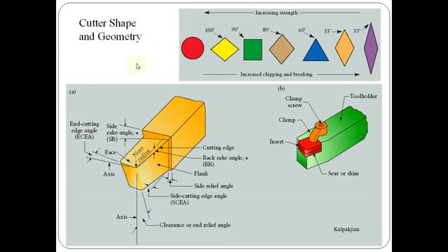So the cutting geometry as well as the shape of the contact point plays a major role. As we see here, as we move from the very sharp end to our blended one, we may have a higher strength, but the sharp end is required for machining. Very sharp, in the sense that the cross section will be the minimum, will result in greater chip breaking. So this kind of shape will be utilized as an insert sometimes, based on the nature of the tool and workpiece material.